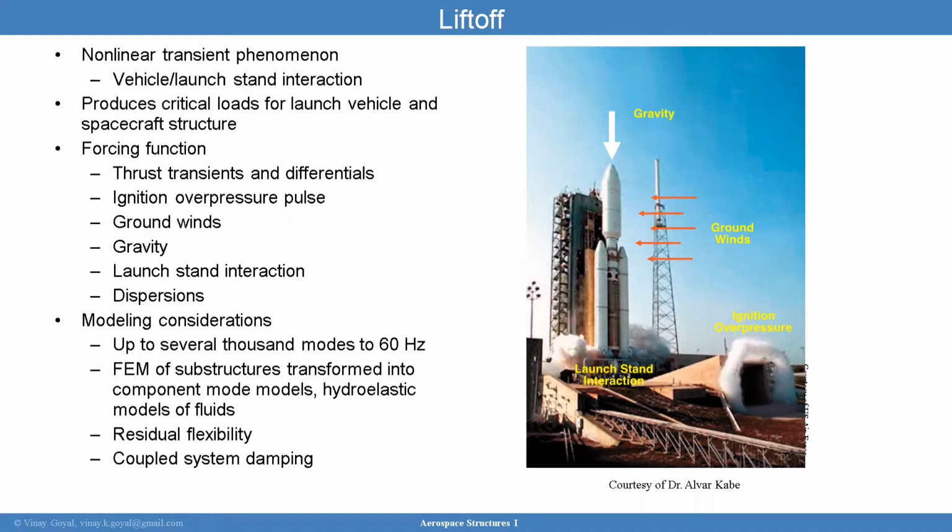So you're actually analyzing time events, and liftoff is one of the events you want to look at. Also, I want to point out that the maximum acoustic environment that is used in acoustic test does not necessarily coincide in time with the maximum transient liftoff loads. It could be a different point in time. And so therefore, the acoustic levels that are proper for the liftoff transient event should be used in analysis. Again, acoustic tests should be performed to verify the accuracy of the prediction process. So that's one thing to really consider as we talk about liftoff here.